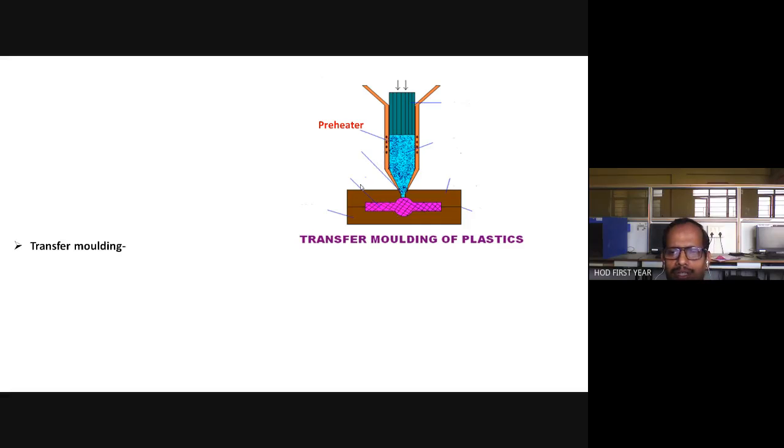construction. First see construction. This is the preheater. This whole chamber is called a preheater. And obviously we have top molding part, then bottom molding part. We have cavities inside. Then plunger to apply pressure, means to push plastic material into the die. Then orifice, we have a small and sharp hole having uniform cross section. We usually call it an orifice. Then plastic ingredients or powder and molding cavity. The labelings are very simple and pressure is unidirectional from the top.